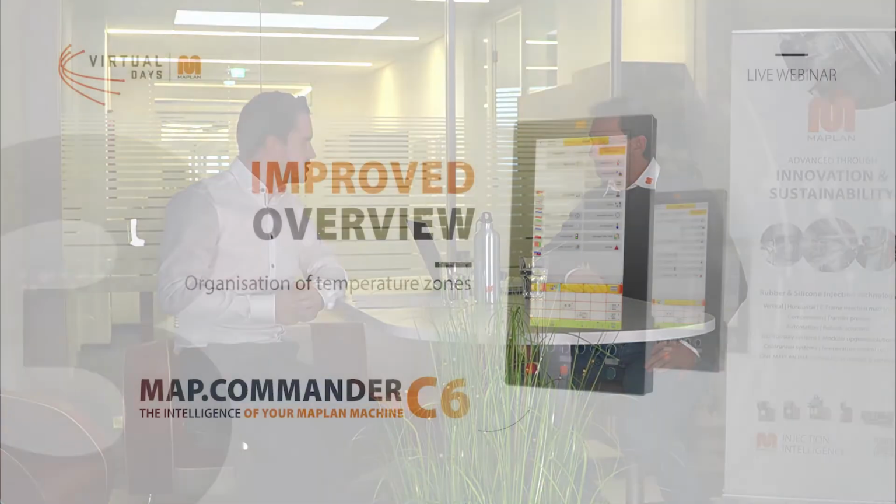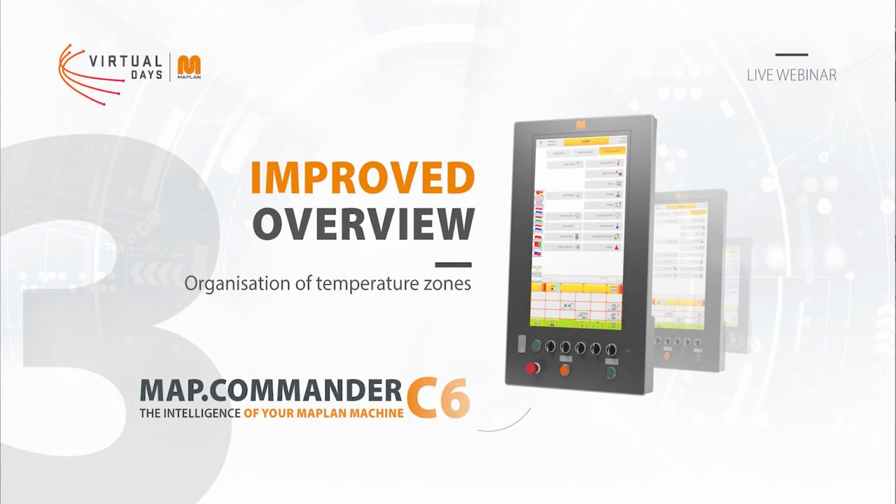Exactly. Great. As we are currently on the temperature pages, I noticed that you put up a nice, defined structure, for example, injection unit, cold runner block, and so on. Could you tell me something about this? I think it's a new feature with the new control unit. Right. So depending on how many temperature zones you have for your machine, it can really make sense that you differentiate or split up your zones in groups that make logic sense to you or to your employees.